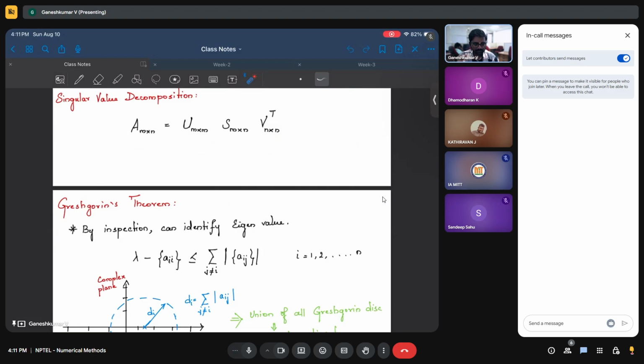You know, for the dynamics of robot motion, when you want to convert the joint space to task space, in those places you will use singular value decomposition. Most of the time your robot will have multiple degrees of freedom and multiple ways it can move. In real space you have only three directions, but the robot can have more than 3 degrees of freedom, like rotation, linear motion, and things like that.